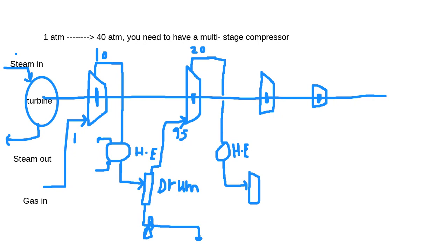Nice. And again the same thing, the liquid goes down, it could be pumped to another process, and then the gas flows to the third stage. The discharge pressure was 20, so the suction pressure could be, as an example, 19.5 or 19, though we usually want a very low pressure drop. And now it flows to 30.